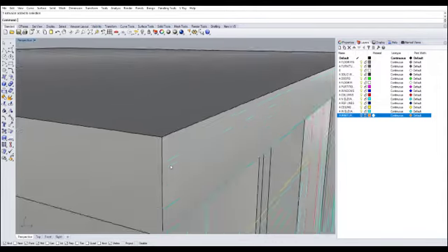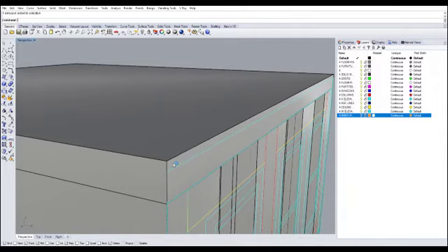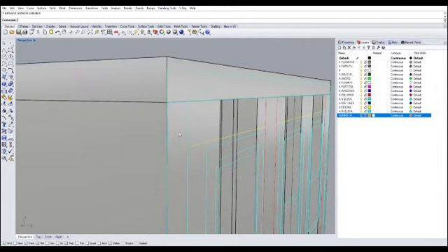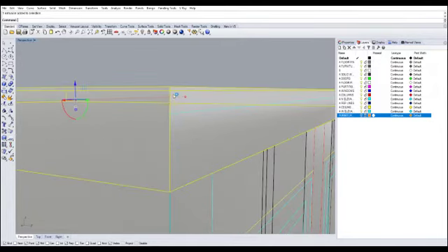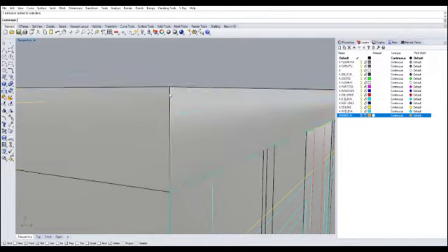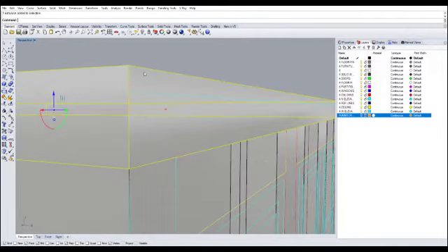So all we want to do is simply shrink the height of this new floor, shrink the height of this new ceiling to the original ceiling elevation line. Which means that we don't have to scale this proportionally, which in 3 dimensions is going to get bigger as it goes higher. We want to control our scale command so that it's restricted to just lowering and increasing the height. To do that, there's a handy scale tool called Scale 1D.